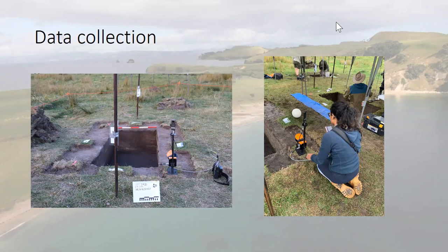When a new deposit was reached while excavating, the surface was cleaned and recorded with photogrammetry, total station, and the GeoSLAM, which is the LiDAR scanner that uses the SLAM algorithm. The photogrammetry was collected with a Canon camera. Targets were placed around the excavation, which you can see there as white, along with two poles at either end of the excavation with more targets on them. And this was done to align the many models that constituted the trench, and also they were done for redundancy. So not all of the targets were used in every model, but there was enough that we could align them all with what was captured.